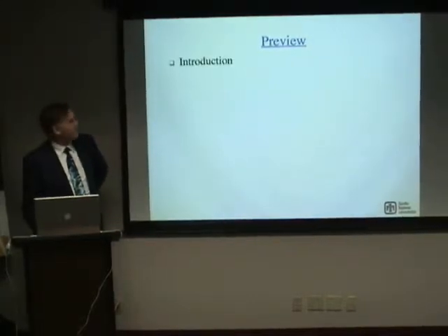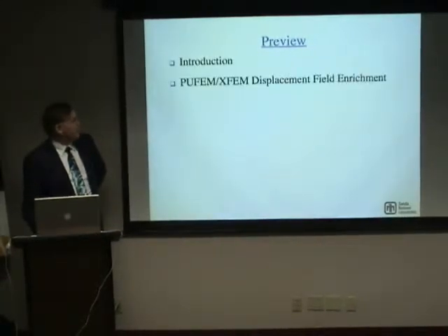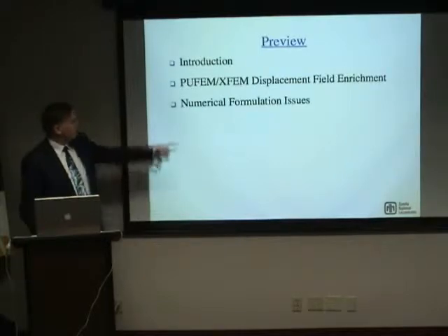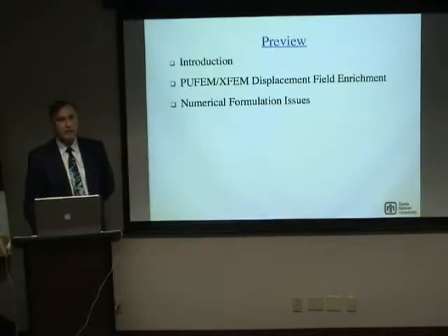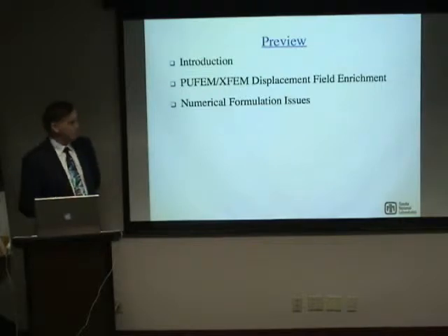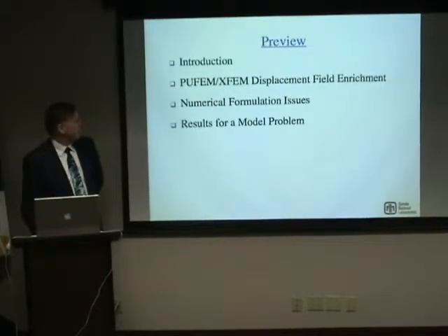Okay, I'll give a preview here, giving a brief introduction, talking about what's referred to as partition of unity finite element methods, and more specifically for fracture, usually referred to as extended finite element methods. X sounds cooler. We actually have a group at Sandia that meets on this topic of extended finite element methods, so I jokingly refer to it as the X-Men support group, which sounds a lot more macho than calling it the Pooh-Men support group or something, so we do like the X better.